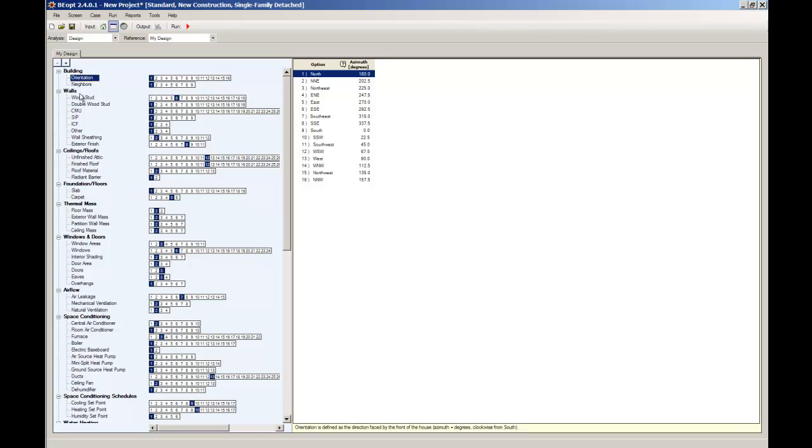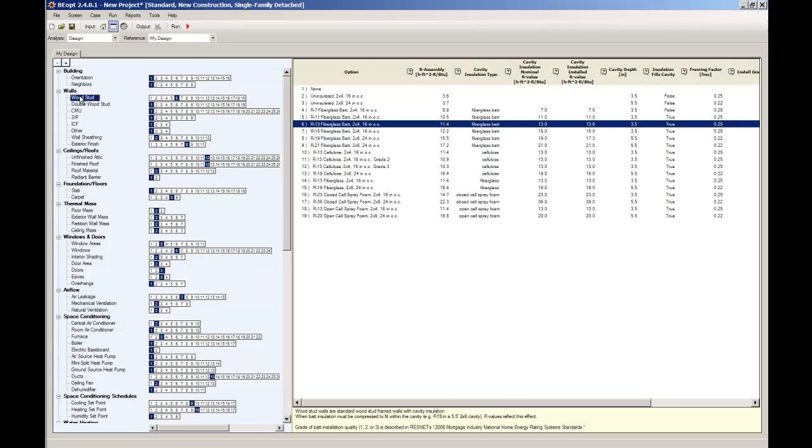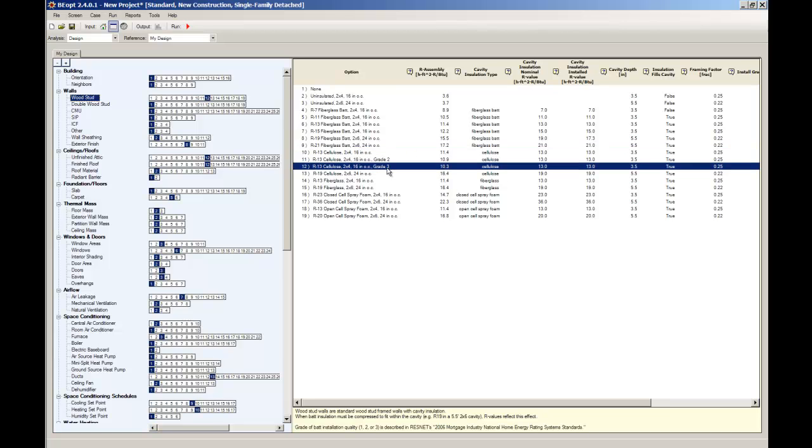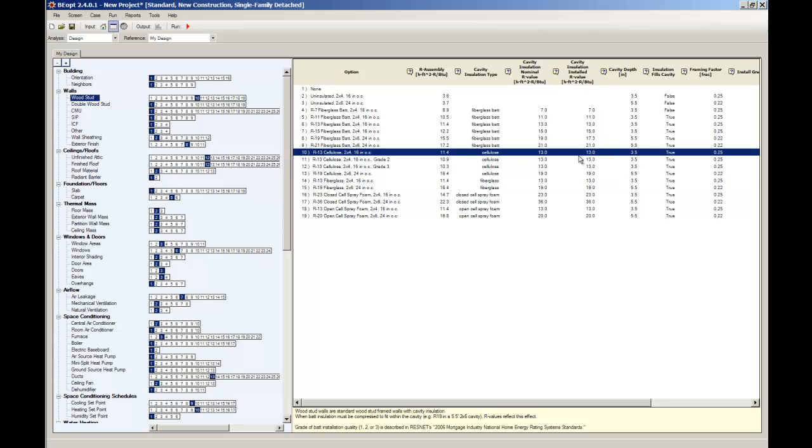So I'm just going to highlight a few of the key ones. For the walls, we want to specify how much insulation is in the walls, and my insulation is not exactly this. It is cellulose blown in, or something like cellulose, and whether it's well installed would be R11, poorly installed would be R10.3, and I'll just pick this. I have 4-inch studs, and that's how much the cavity depth is, etc. That's roughly right. I'm not a double stud wall. I don't have any of that, so I'm going to mostly skip that.